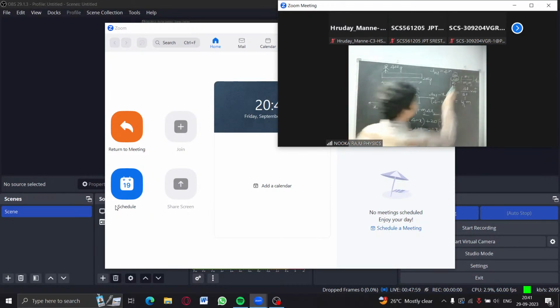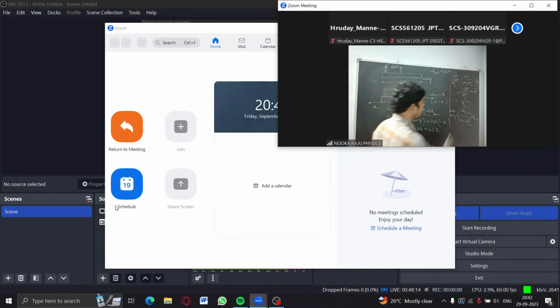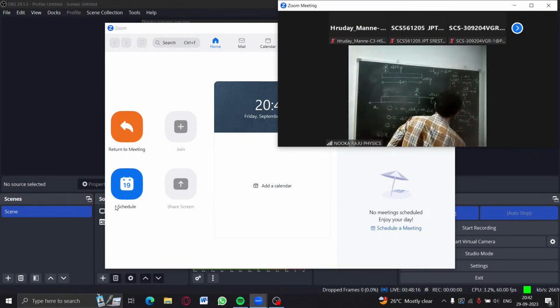And what about the distance of M1? I gave the shortcut relation. If you are considering M1, what is the formula? M2 by M1 plus M2 into D relative. What about this value? 20 by 60 into 4. 0 cancel, 2 2s are 2, 3 2s are 6, so finally 4 by 3 meters.